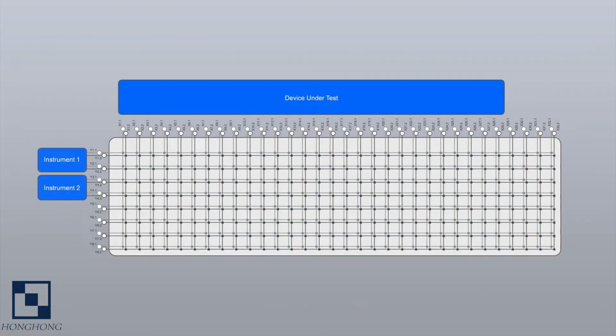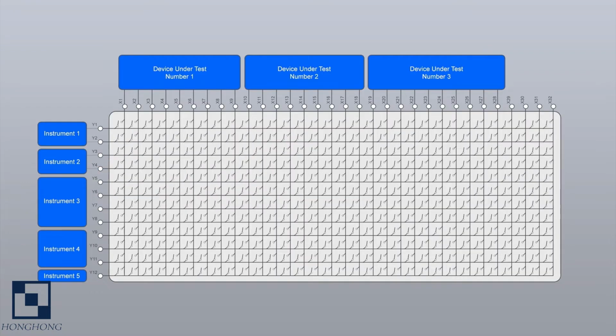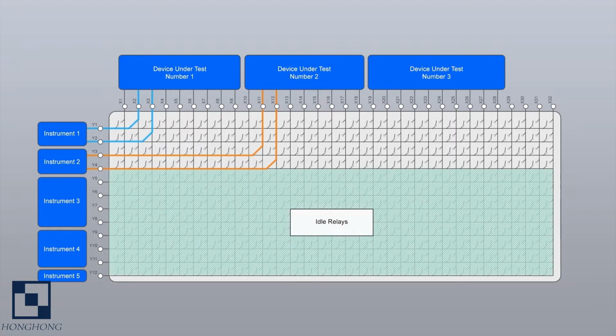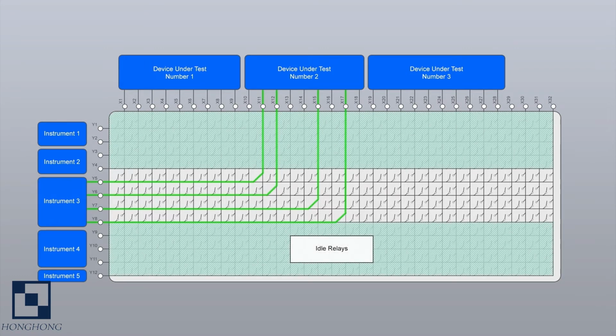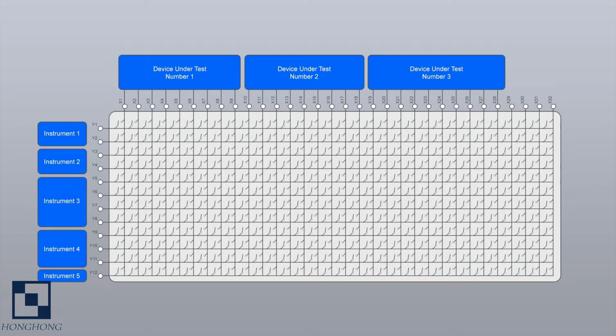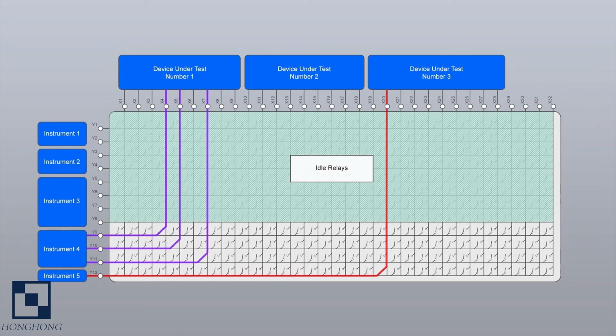Here, two-pole relays are used at each pair of matrix crosspoints, and both signals are switched by a single software command. Although it is easy to visualize a matrix with instrumentation and device under test connections on separate axes, this is not always the most efficient way of doing things, especially when a large number of instruments are required. If each instrument has a dedicated matrix row, and only one or two instruments are used at the same time, there are a large number of relays standing idle throughout the test procedure. These relays cost money and should be employed as much as possible.